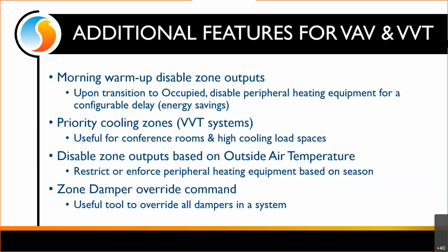We're also able to enforce certain peripheral heating. So let's say we have a large showroom which has a lot of windows, and maybe we have a modulating three-way valve for some baseboard heat.